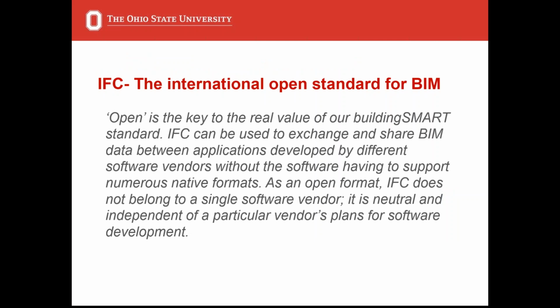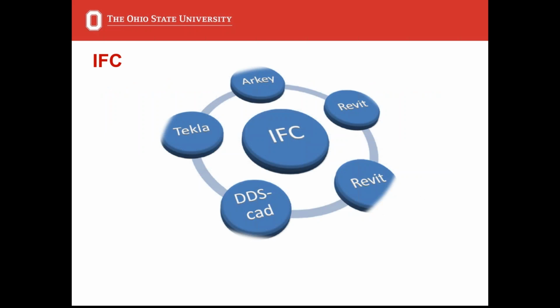So for us, our option is to look into the IFC. IFC is vendor neutral, software neutral. It can be interrogated by some of those other software applications so that hopefully we can pull out that information that we need. That's mainly what we're using as far as exporting out of Revit. You can see it's then software neutral.